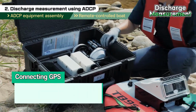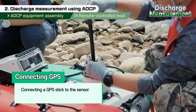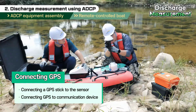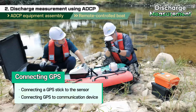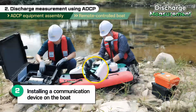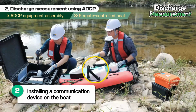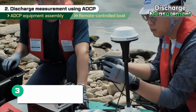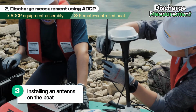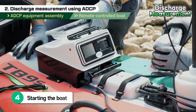For the GPS, first connect the GPS stick to the sensor. Using a cable, connect the GPS with a communication device. Install the communication device on the back of the boat and connect it to the ADCP through a cable. Next, the on-site worker installs an antenna on the boat for transmitting measurement data. Next, the battery is mounted on the boat.